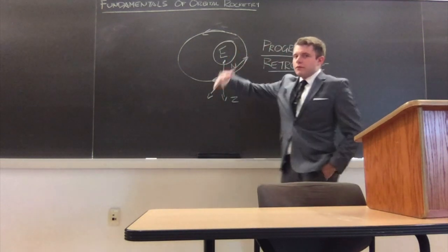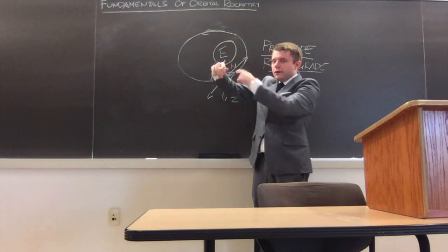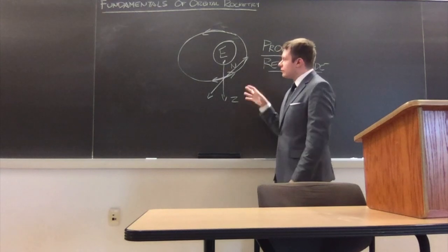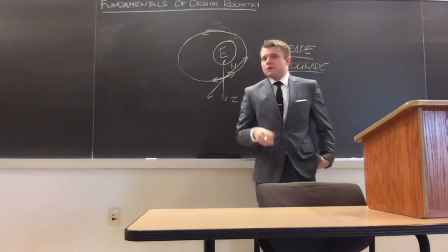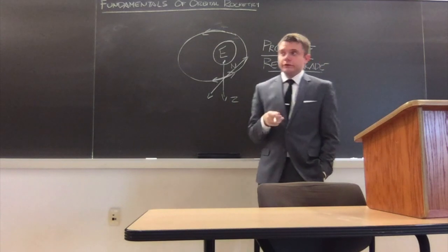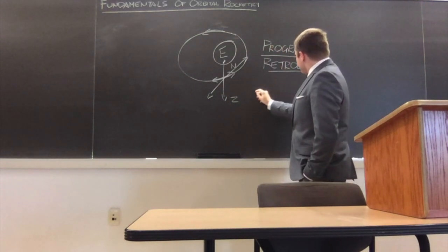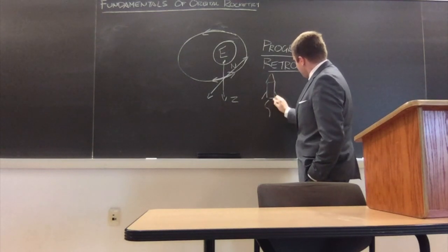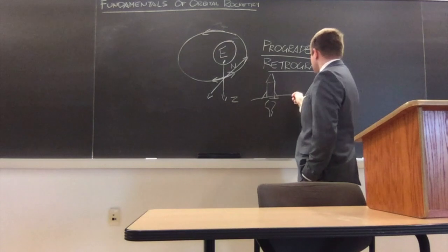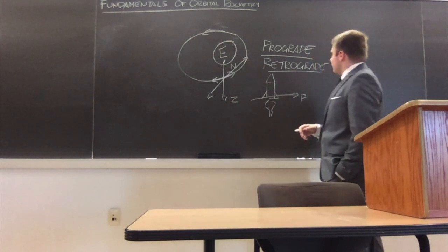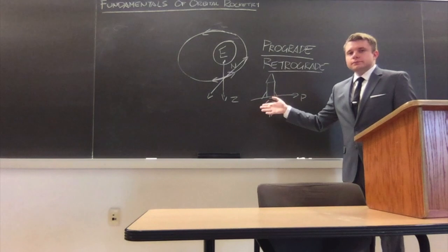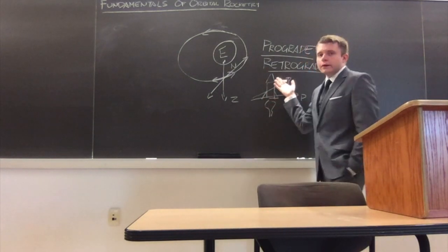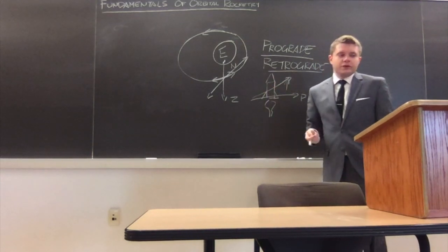Basically, if you have the reference plane here, normal is coming out at you, anti-normal is going away from you. You might ask, what happens if you point your rocket in those directions? I'll specifically talk about normal and anti-normal because it'll launch directly into our next topic, pun intended. If you point your rocket upward, out of the plane of the orbit, you basically change the inclination of your orbit. You add a new vector, and the sum of those two vectors means that you're now in an inclined orbit. Congratulations. Nice, simple, and straightforward.